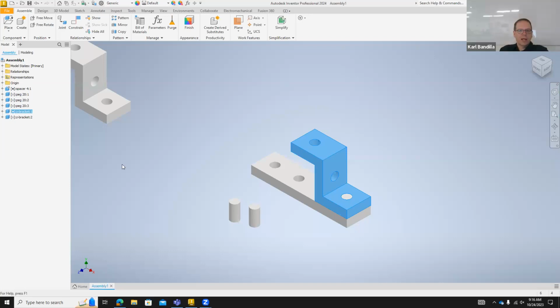All right. If we look at relations, when you're done with this, you should always have a quick look into this little folder, because for some of you, I saw all kinds of stuff in here. There were a whole bunch of warning signs in there. There were types of constraints that we never used before, people clicking on joints instead of constraints, those kinds of things. So if you want to double check, you can always see that here. That's a good thing.